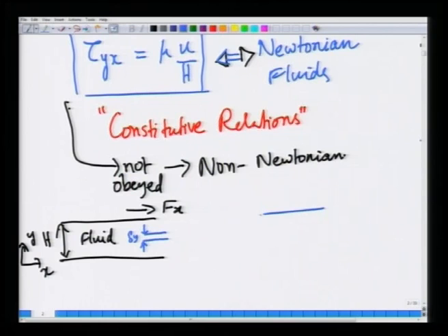So, essentially, if you recall, we are extending everything in the z direction. So, this is a tiny slice of thickness delta y in the y direction, okay. And you can try to apply. So, when the fluid is stationary here, the fluid is moving with some velocity here, okay. So, if you were to plot the velocity, the velocity will go from 0 to some velocity u at the top plate in this example, okay. So, fluid layers are sliding past each other in this simple example.